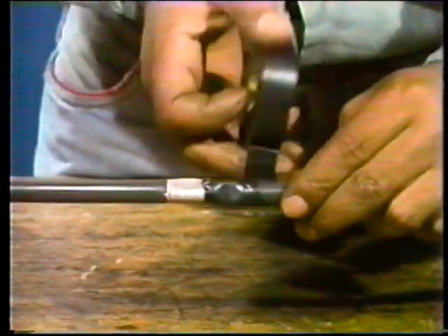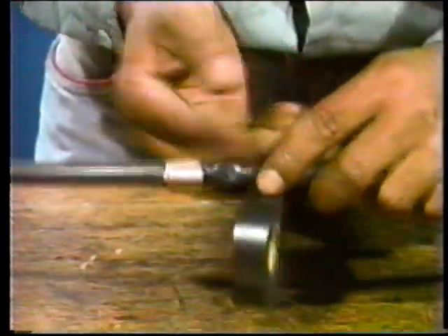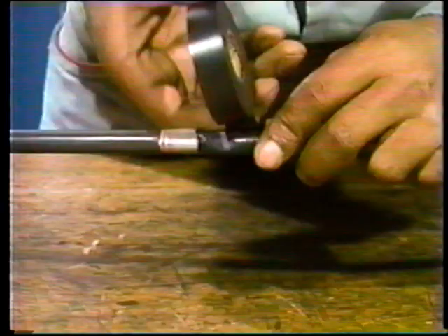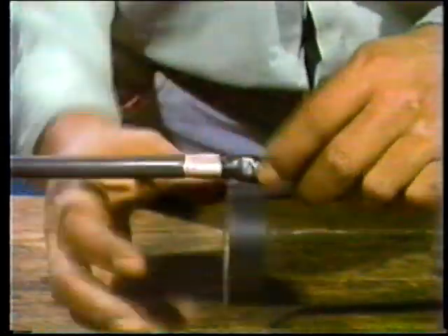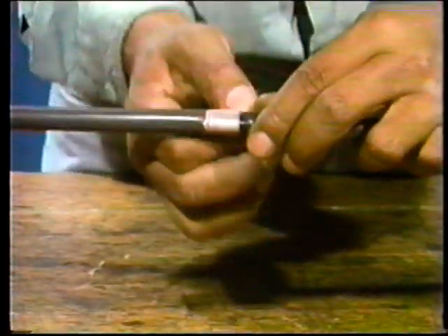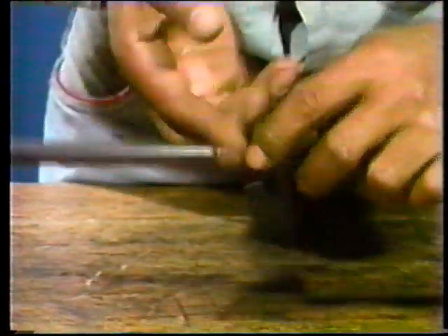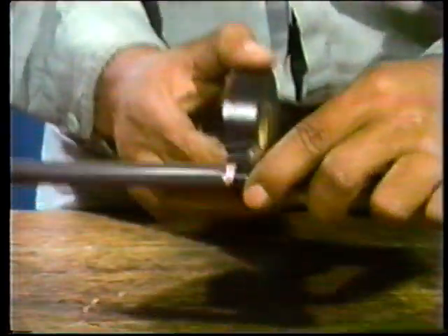Bill will put at least 3 layers of tape on the splice. This will ensure that he surpasses the mechanical strength of the original insulation. He'll start in the center of the splice and then go out to about 1 inch beyond the insulation that remains on the conductor. Then he'll work his way back across the splice and out to 1 inch beyond the original insulation on the other conductor.